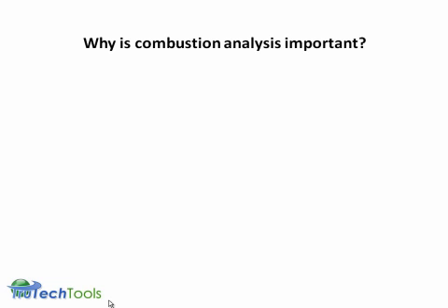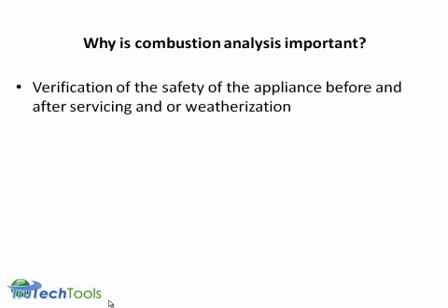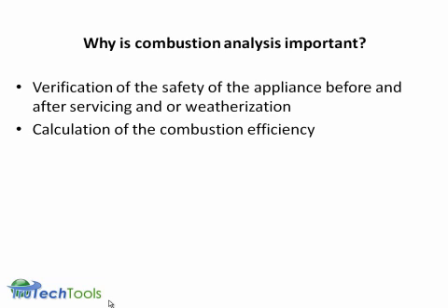So why is combustion analysis important? Well, first of all, we want to verify safety of the appliance before and after servicing. And this is especially important as we weatherize homes and tighten things up. We want to make sure that we're not creating an environment that's dangerous. We want to calculate the combustion efficiency and see what that's running.